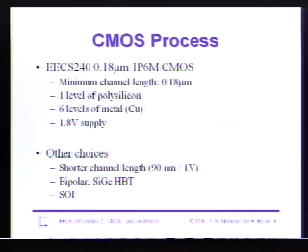For now, we want to stress the fundamentals, and if we go to finer line technologies, especially voltage headroom becomes a big issue. So using something mature like 0.18 will let us get around those issues. We're not going to use other technologies, including bipolar, silicon germanium, HBTs. We'll talk about them once in a while and compare and contrast them, but the focus will be CMOS technology.